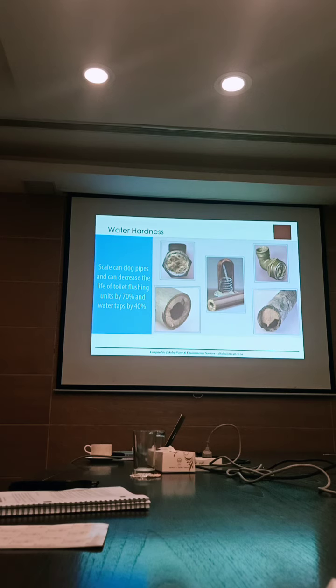You're paying for water that should be of a certain quality, that should be non-scale forming. Which is more cost effective, the descaling process or the softening of the water before? I think you need to look at the entire life cycle cost of descaling against putting this in as a once-off process and cost. I can't tell you what it is.